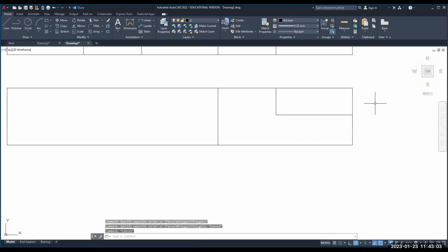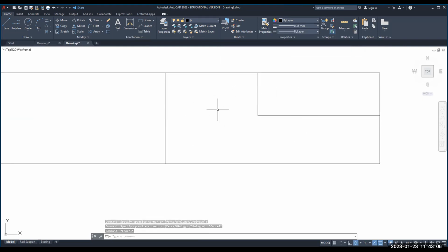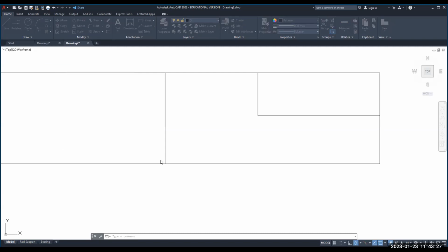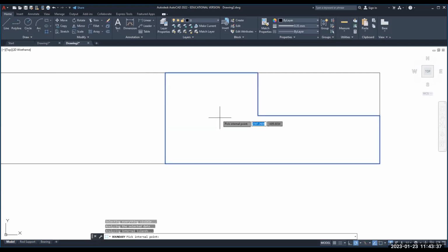All right, so if I wanted this area hatched, the easiest is boundary hatch. Is this hatch? Yeah, this looks like hatch. So to type it, it's B hatch, right? And again, if you don't know how something works, just leave your mouse on it, it'll tell you about it, but I'm going to click boundary hatch. Picking points is the way to do it. That's how you identify the region you want. So picking points is already chosen. And you just pick in here and it's going to find that boundary for you, right?